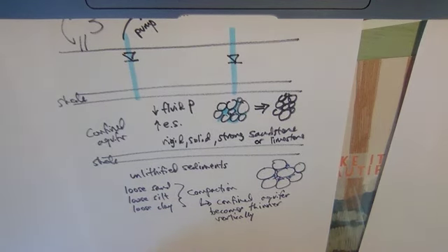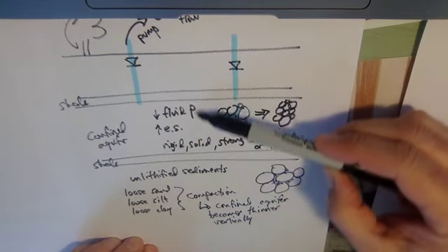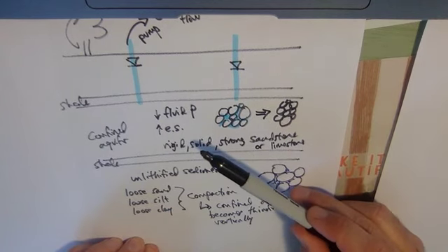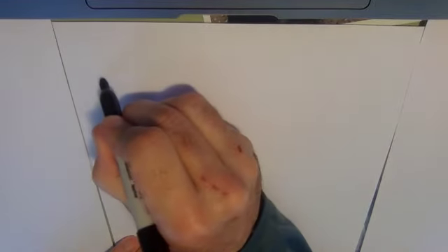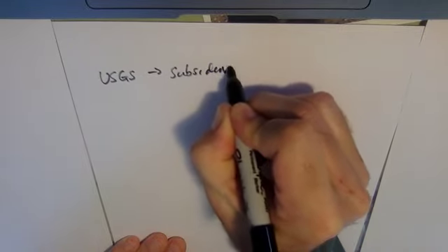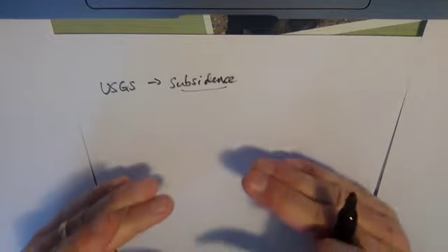And that may not sound like, I mean, who cares, right? Well, it turns out that when you have really, really compressible materials, like clays and silts, and you have really thick deposits, as you can get in some parts of the world, and you pump a lot of the fluid out, which has been done, you get a lot of compaction. And the consequences of that are pretty remarkable. And you're going to read the USGS reading titled Subsidence, which will be posted if it's not already to Moodle. Because what subsidence means is the land surface actually subsides as the underlying rocks become thinner and thinner.